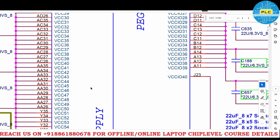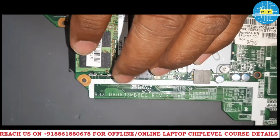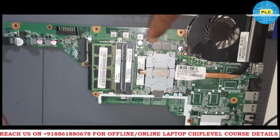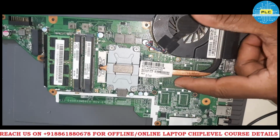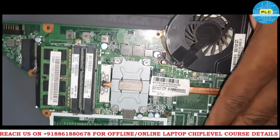I'll do one thing in the motherboard, just a section I will explain to you. What is that VGA core, VCC core, and graphics core, whatever it may be, I will show on the motherboard. Here is the motherboard. It's an R33. See, the motherboard part number is R33 MB. Okay. So now see, some coils are there here. This is a CPU part, but here there is no graphics chip. The discrete one which you mentioned now is not applicable in this particular motherboard.